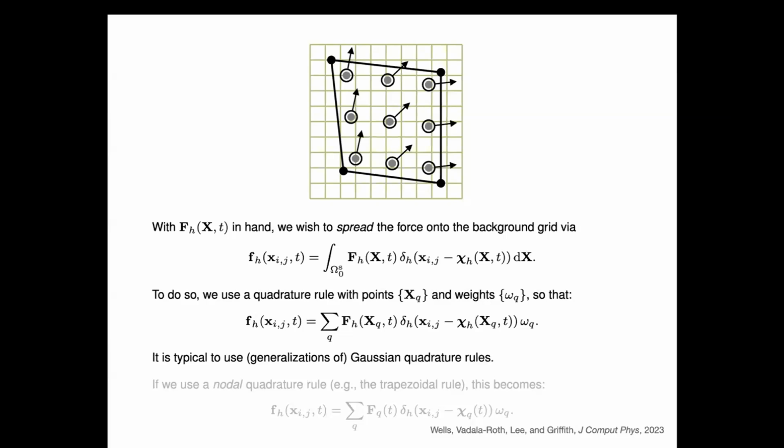And it turns out that works okay if you don't have big pressure loads, but it doesn't work very well if you do have big pressure loads. And so a lot of it just depends on what you're trying to model. But if the mechanics are such that you have a big pressure difference as you go from the inside to the outside of the structure, you need to put these nodes close together anyway. And so as soon as you have to put the nodes close together, you might as well just use a nodal scheme. Does that make sense?